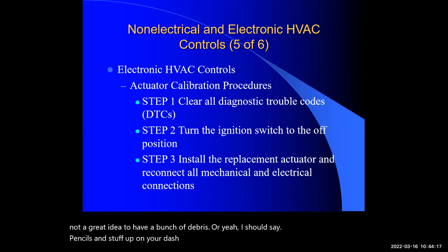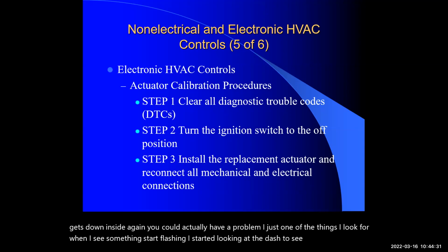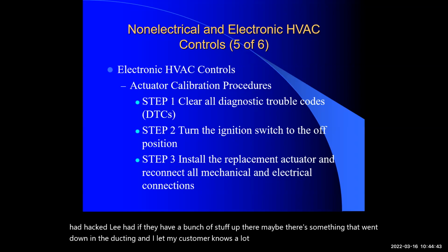We all want to have our fun stuff, but if that stuff gets down inside, you could actually have a problem. It's one of the things I look for when I see something start flashing. I start looking at the dash to see if they have a bunch of stuff up there, maybe something that went down into the ducting, and I let my customer know at the very beginning. Back to it.